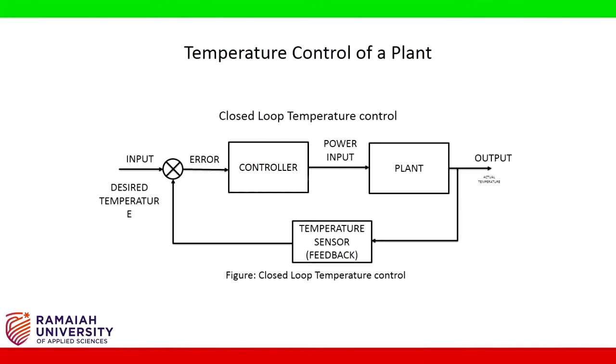To make the control effort, that is, the amount of fuel fed to the furnace, for example, proportional to the error, that is the difference between where you are and where you want to be. And there are other algorithms that use the error or some function of the error, like the integral of the error, for example, to calculate the control effort. An automatic controller does the same.